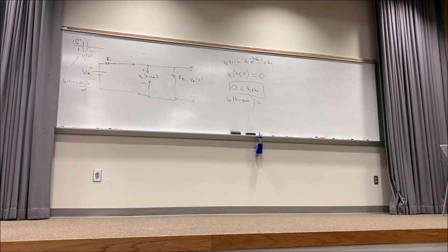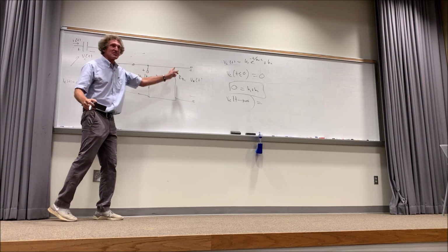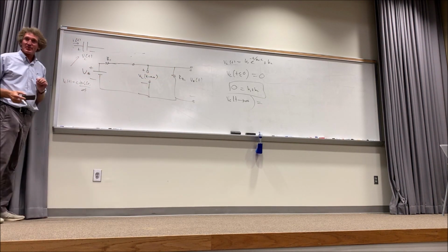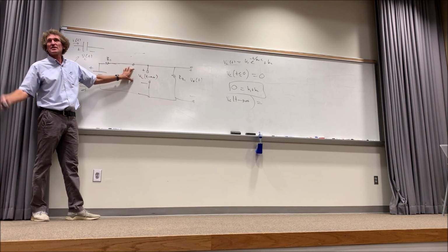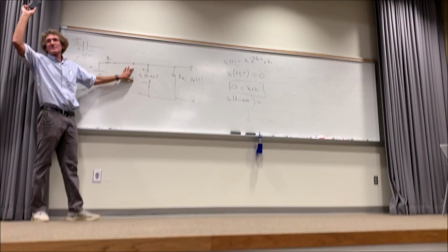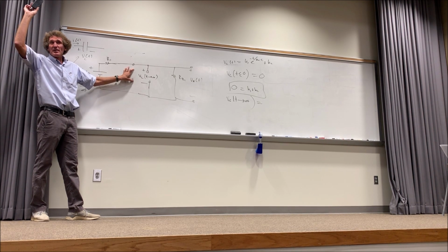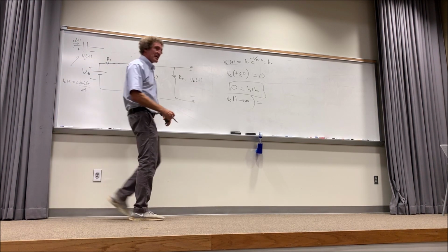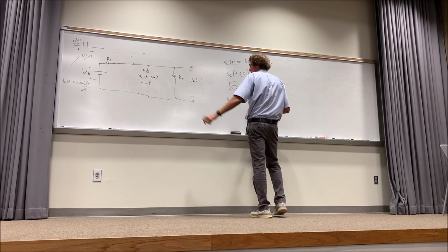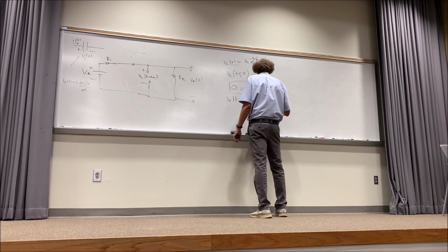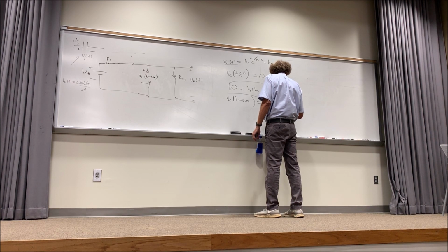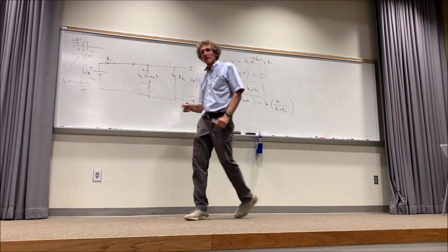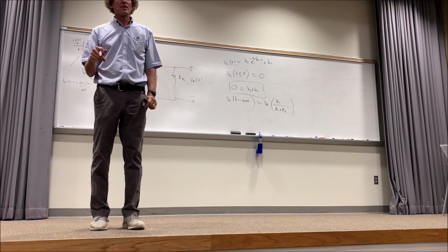Yeah, kind of. But isn't this voltage division? Don't I have one resistor in series with another resistor with one source, right? And isn't the voltage across this resistor the voltage here, class? How many see this? I'm just trying to make sure you all see it. Well, what is that voltage? Isn't it just whatever the battery voltage is, V naught? And then it's voltage division. Then it's simply R2 over R2 plus R1. Do you all agree? Everybody? How many see this?